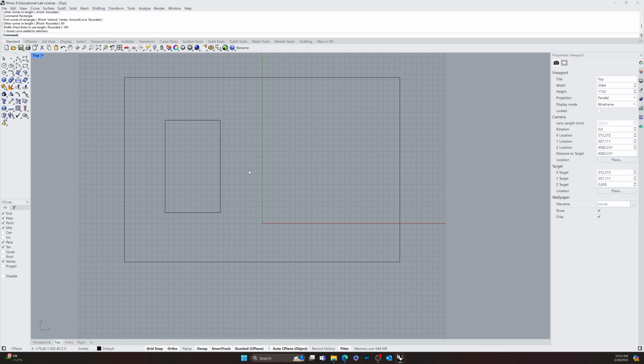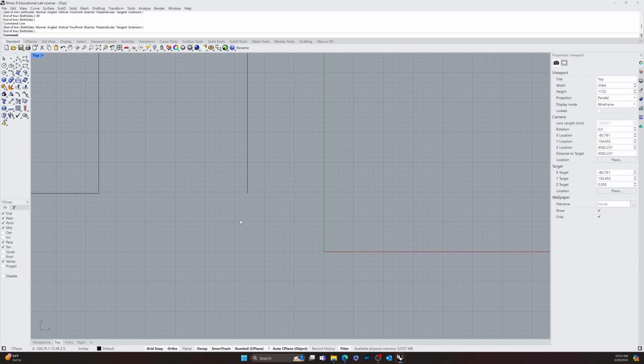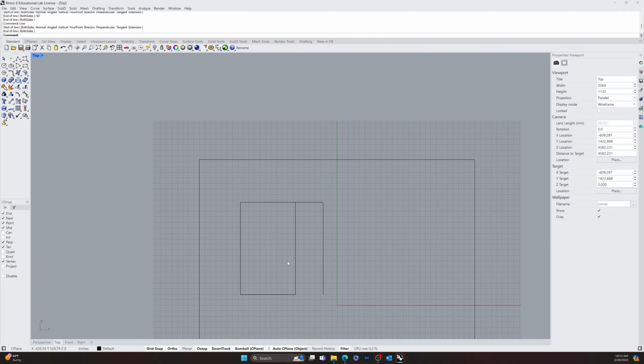Maybe let's do like 60 feet from the middle here. So I'm going to do a line from the midpoint, 60 feet this way, and click. And just remember, have your snaps on, not the selection filter, but the snaps here, making sure that you've got at least the ones I've got on, so that you're kind of locked in here. And then I'm going to draw a line down here. I'm going to touch over here and drag out to perpendicular so that I know that I've got it at the same spot here.